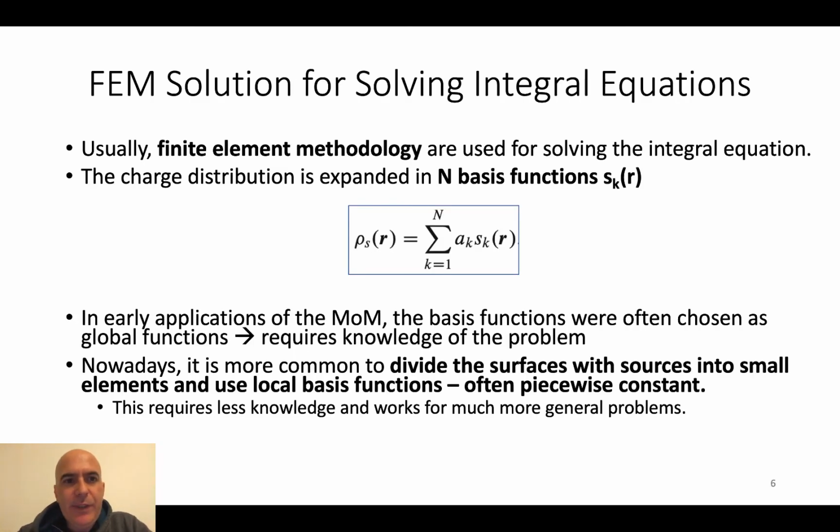So how do you solve the integral equation? This is the second part of the lecture, that is about the method of moments itself. So when we use the method of moments, we use a finite element methodology, right? So it's a kind of surprise. It's called method of moments, but method of moments is basically just applying the finite element method to the integral formulation of a given equation. So we use the finite element methodology for solving the integral equation.